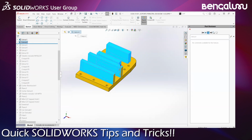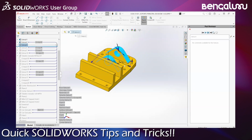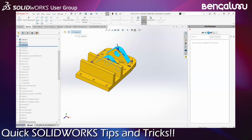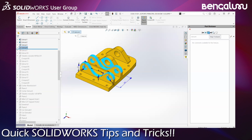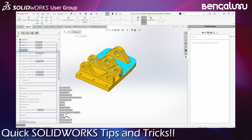So I go to the next step, right? So you can see it. All the dimensions that have actually been added at the sketch level are also visible along with the feature. And that's actually useful when you want to review a part. So, okay, what is the hole size? 85. You know clearly that it's 85. But when you do it from here, you don't get that information. You have to actually click on the feature to review it, right? So this makes it easier for you to review step by step all the features that you or someone else has created, making it more effective, actually.